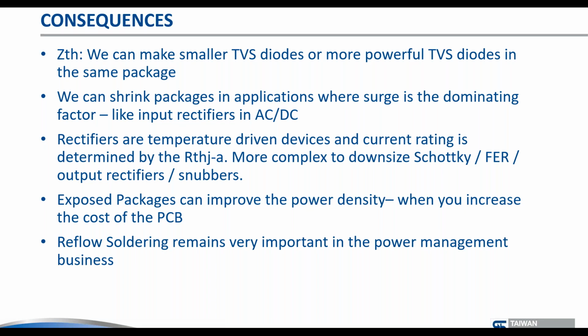of the PCB. And then one thing we would like to mention here, because that's not always so clear, is that wave soldering remains very important in our business of rectifiers. A lot of converters have the storage capacitors there, the big capacitors, they have the inductors or the isolation transformers there. So there are bulky components there that are wave soldered.